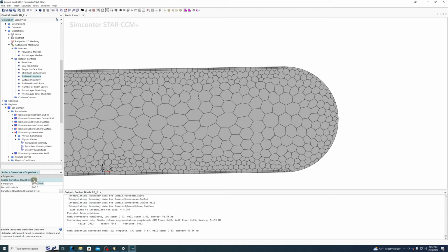So if you activate that, you get a couple more options. Usually you don't need to mess with these. Usually just having the default 36 points per circle is enough. If you want it to be more accurate, you could turn that number up. It's usually not necessary.